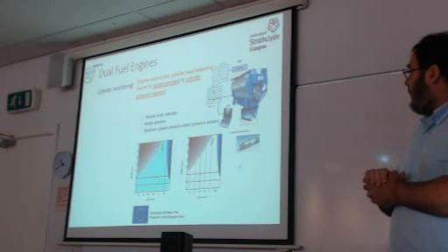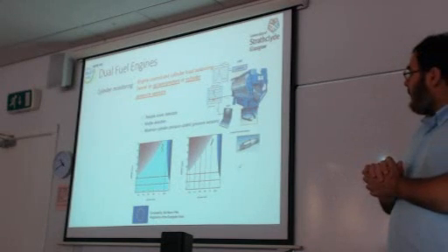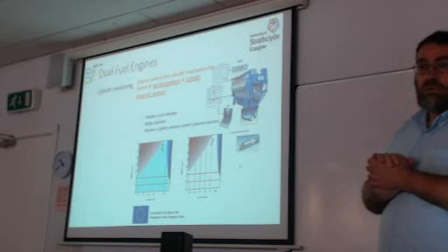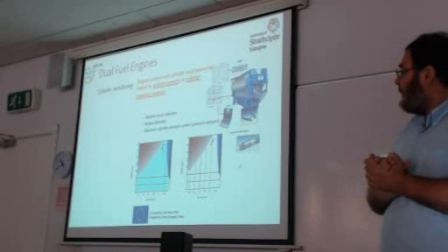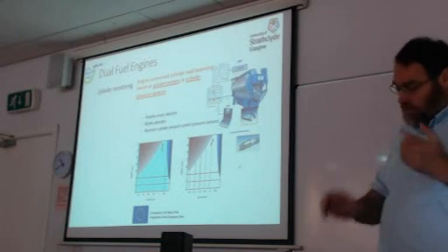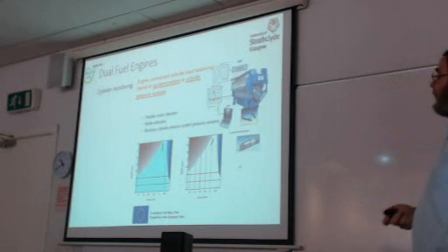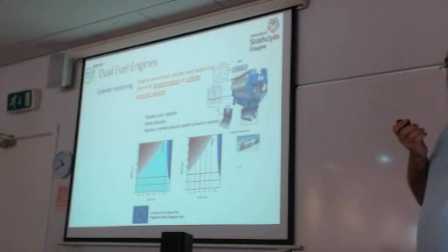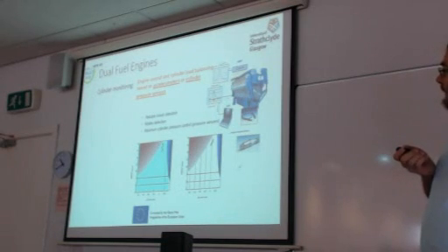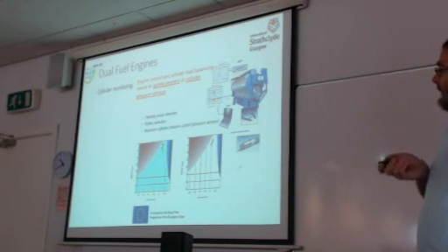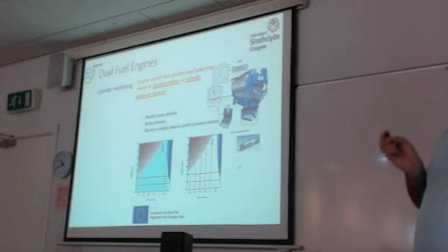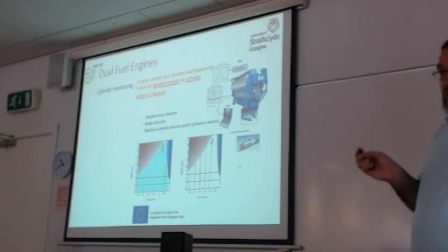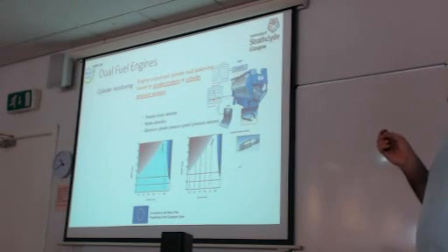Why? Because the turbocharging system, which provides the air to the engine cylinder, needs to be suitably selected to accommodate the engine operation at dual fuel mode and at diesel mode. So there are two different concepts, diesel mode and dual fuel mode, and of course a compromise needs to be made there as far as the turbocharging system is concerned.